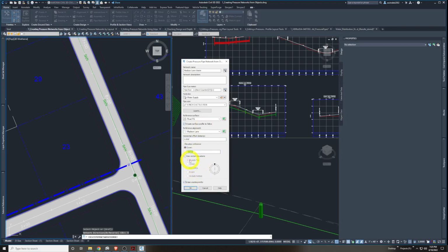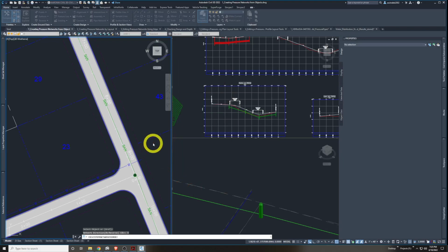Here is where the cover, the amount of ground that is buried over the pipe, is set: 3 feet. We're going to say it's 3 feet still, and it will set us up with that as our starting design criterion for keeping the pipe at the right depth so it doesn't freeze. In maybe the city of Missoula, or where we are in the northern hemisphere, a lot of times you have to keep some of these pipes buried 6 or 7 feet in a lot of these different areas. There's all kinds of design considerations with that, but 3 feet is fairly shallow for some winter climates, for example. Let's hit OK.